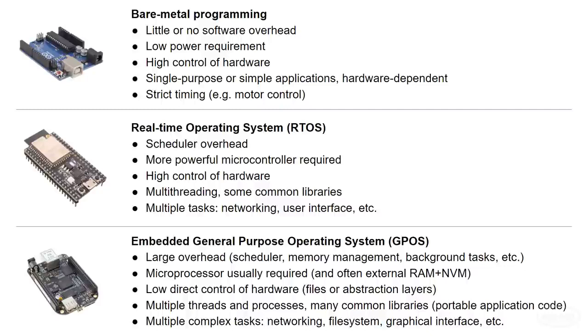However, because of all this abstraction, you lose out on direct control of hardware and it becomes difficult, if not impossible, to meet strict timing deadlines. You have the option of writing driver code yourself to have better control of connected peripherals, but one of the big reasons to use an embedded OS is so that you can leverage code written by others.